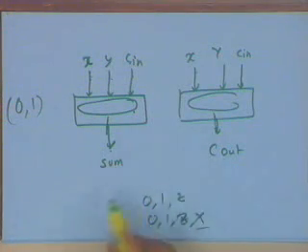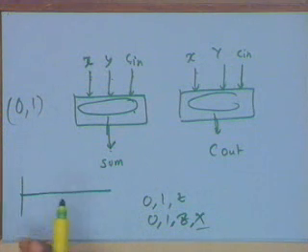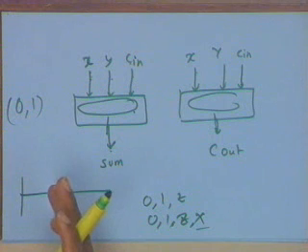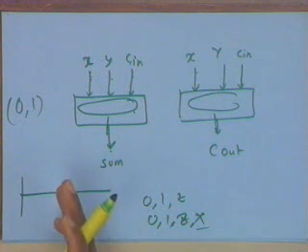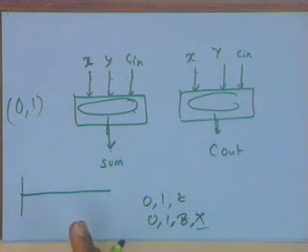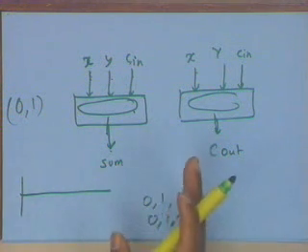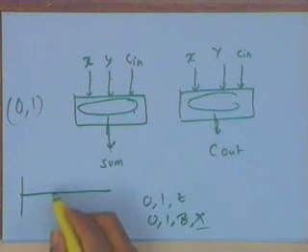In terms of your simulator, the semantics of the VHDL model comes from simulation. The language was essentially designed for modeling, so the simulator is the driving semantics. That is the problem: when you talk of synthesis and use VHDL in the lab for synthesis, you have to be careful.